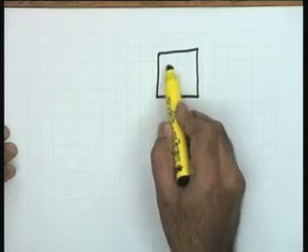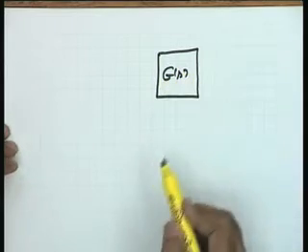Let me take up the aspect of steady state accuracy. I have taken it earlier, now I just give it a different quantitative color. The word steady state accuracy is not new to you. You know that by final value theorem you can determine the steady state error of a system. So let me give some quantitative information about it as to how to handle it when we enter into a design cycle. For that, for this quantitative description, I take this block diagram.